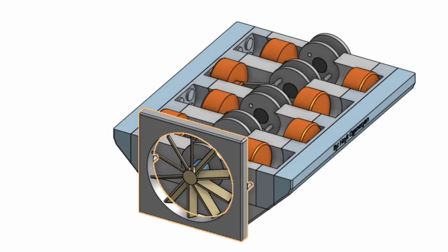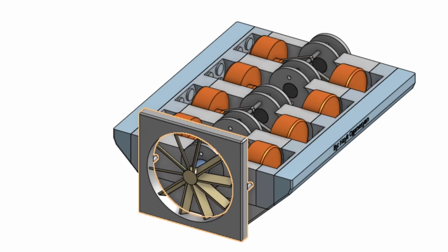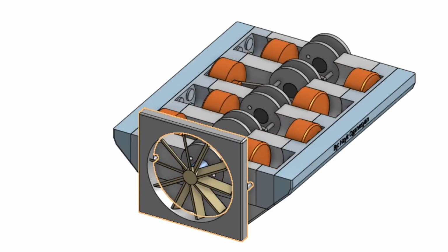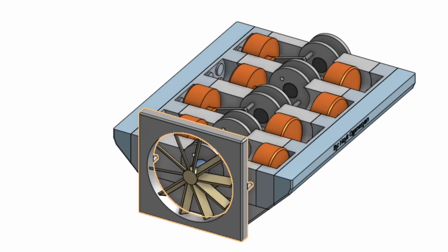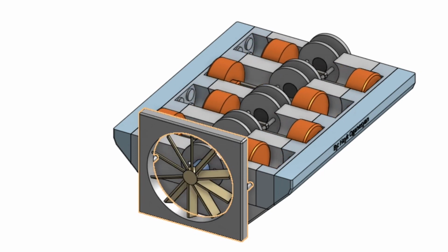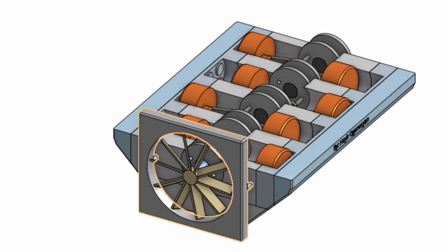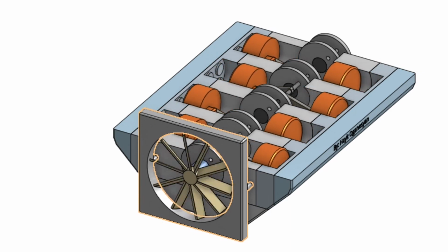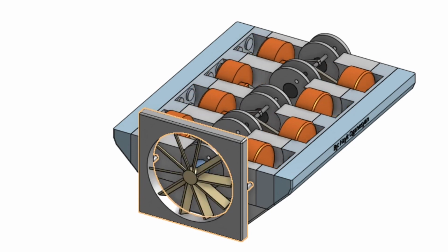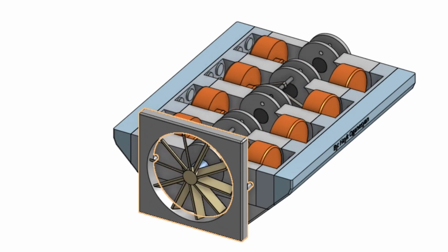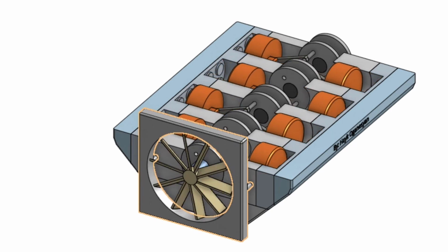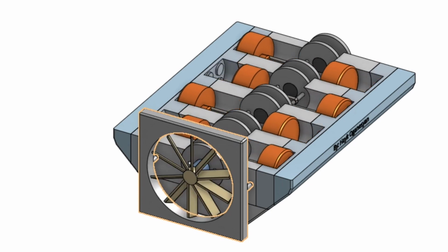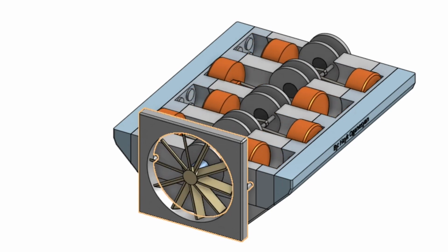Last but not least, the boxer engine. Now this engine is kind of like a V configuration engine, except it has a much lower center of gravity because the cylinders are laid on their side. So kind of imagine taking two inline engines, but instead of sticking them together in a V shape, they're laid on their side. The boxer engine does have a benefit of its own. Because the cylinders are laid on their side, it has a much lower center of gravity because the engine is more compact and isn't as tall as a V configuration engine. So the handling of the car is going to be much better because the center of gravity is lower.